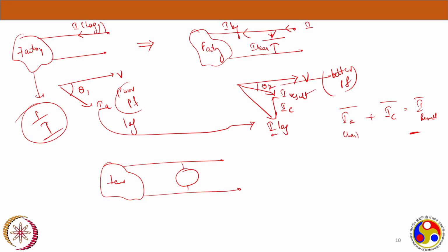Always operate your synchronous motor in the overexcited condition so that it will always draw a leading power factor. So based on the load changes also, your synchronous motor is adaptable to it. You just have to go for another excitation.